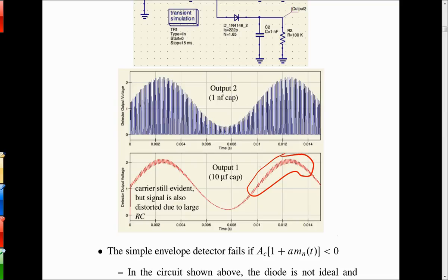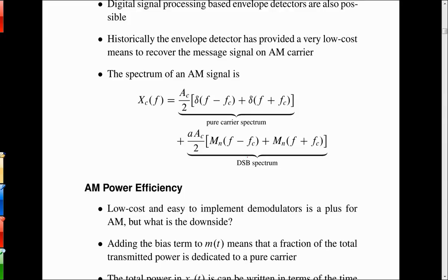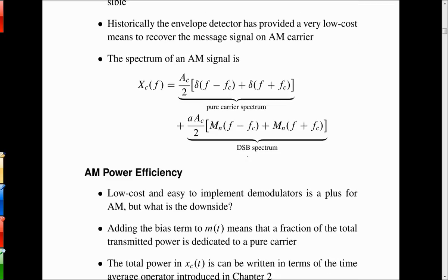But if you send it into an audio amplifier or headphones, it will reject it, and your ears don't hear it anyway because it's above what you can hear with your ears. But you don't want too much of that coming through because that could overload your audio amplifier if it could respond at that higher frequency. Or create intermodulation and all those other bad things we talked about if it overloads it. The spectrum is like I was showing in the picture earlier. It's the double sideband spectrum overlaid with two spikes, positive and negative frequencies for the carrier.